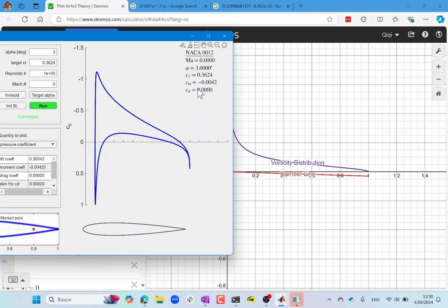26% from the leading edge, right? Not from the quarter chord. Okay, so how is the calculation done? The calculation is done by CM divided by CL, and you subtract this from a quarter to get about 26%. So this is how much error we get from thin airfoil theory. Thin airfoil theory predicts 25%, and in the real airfoil calculation, we get 26%. This also gives you a sense of the accuracy of thin airfoil theory, how much you expect in this case. All right, any questions?